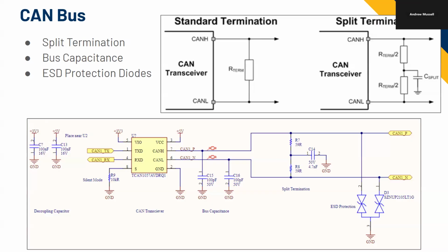You can get PTC resettable fuses, which are a different type of component that will heat up too much, stop conducting current, and then later cool down and continue conducting current. You can use those in some places. There are a lot of places in the rules where you can't use resettable fuses. They only want fast-acting, one-time blow fuses. But the thing these do is that the fuse is going to add resistance into your line, because it has to heat up to burn, right?